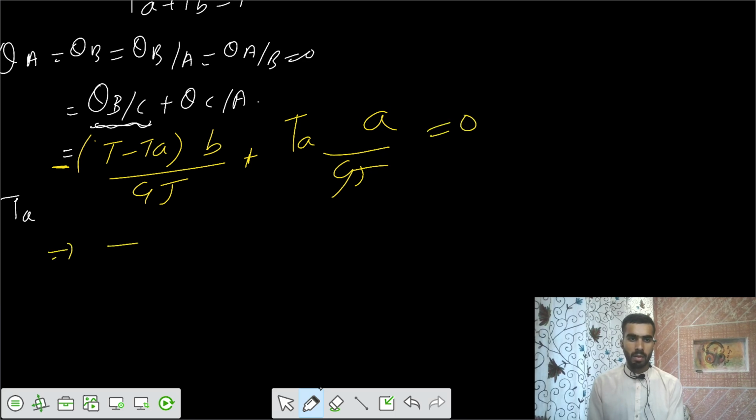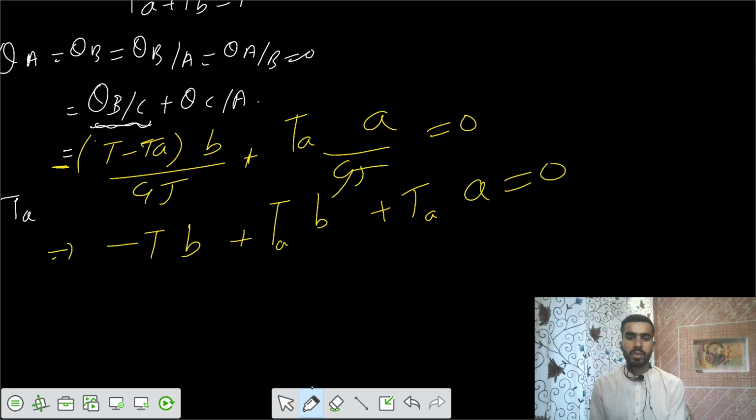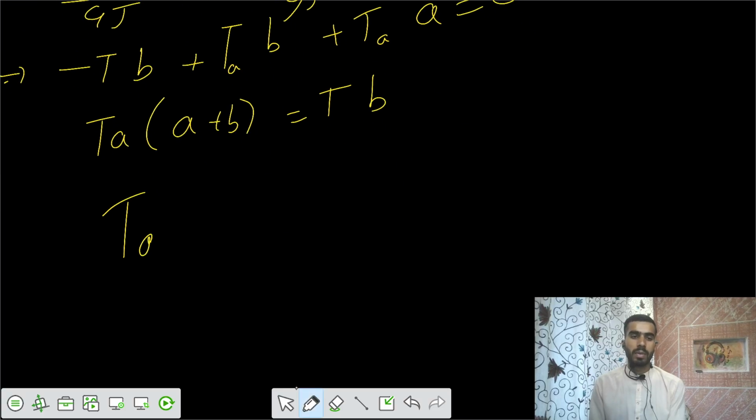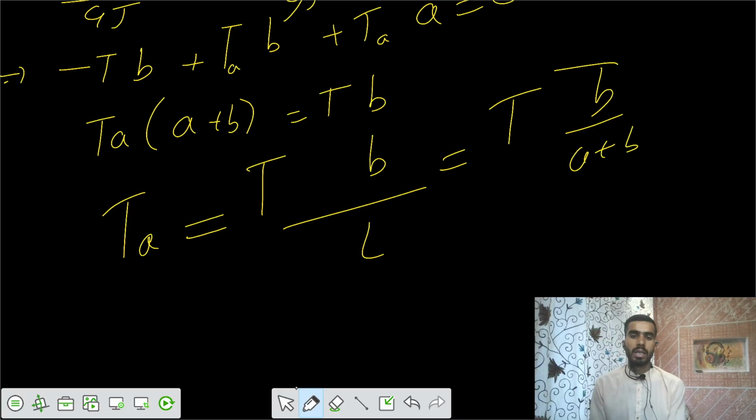So you got minus (T minus TA) times B plus TA times A equals 0. So you got TA times (A plus B) equals T times B. So the torque developed at A equals T times B by L, or you can write it as TB by L.